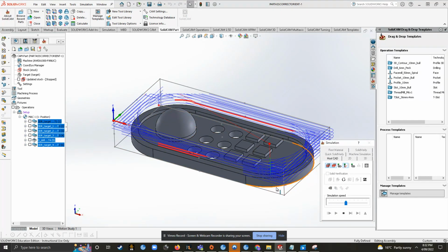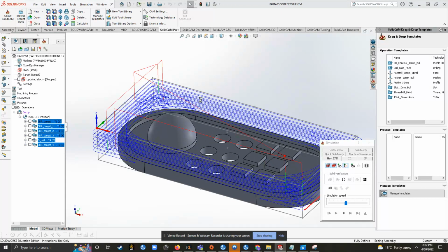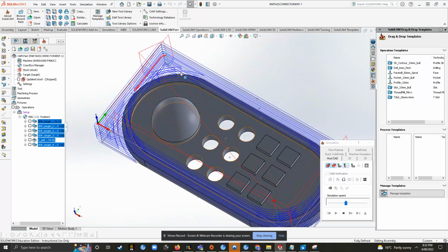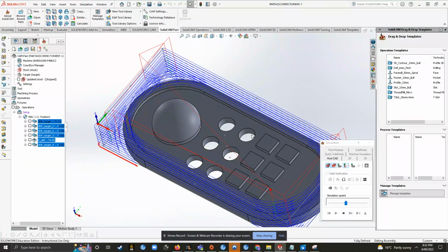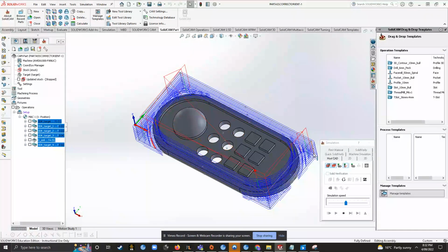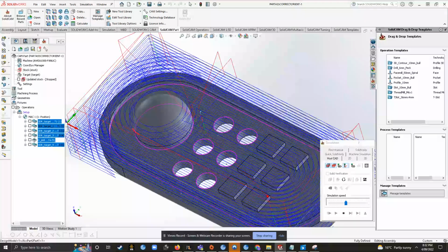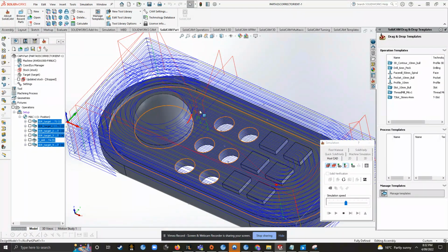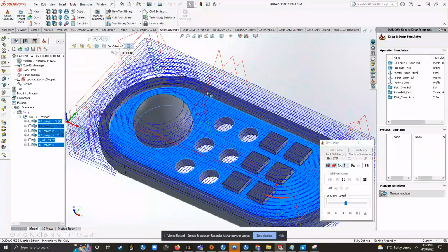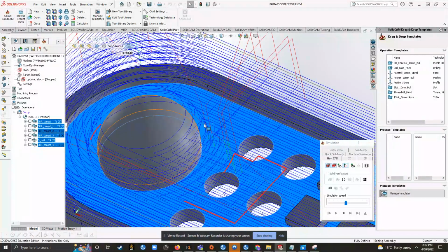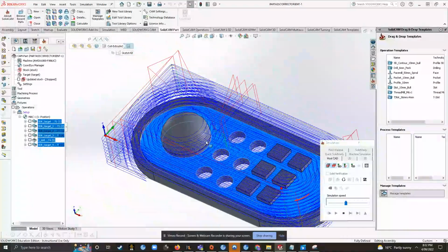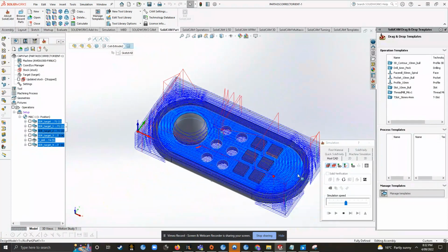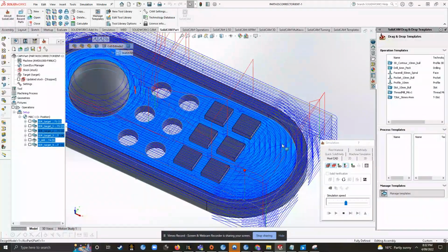So first we just milled out that curved rectangular profile out of the rectangular stock piece. And second is just milling down to that first level there, leaving a wide distance here between the spherical shape and just doing regular milling down to this wall level.